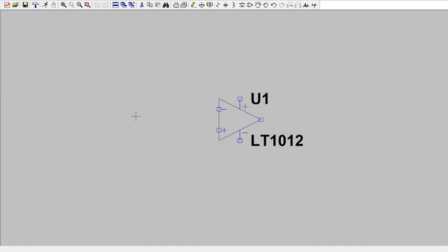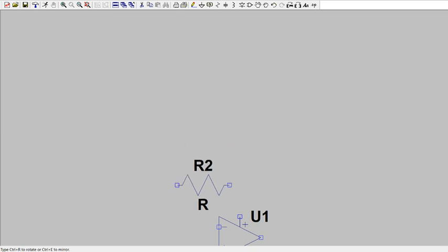And we need resistors, correct? So we're basically building an amplifying circuit. All right, so let's use some resistors. Go ahead, get the resistors. I'll place one here, and now I need to rotate this. I want it horizontally. You can do two things: you can do Control R, or you can click this rotate button here. I'll just place it here for now and click escape.